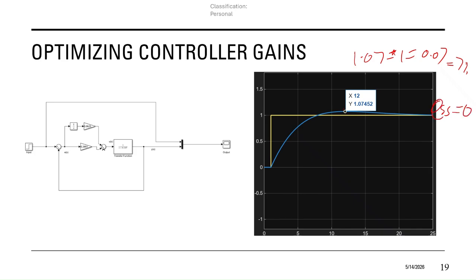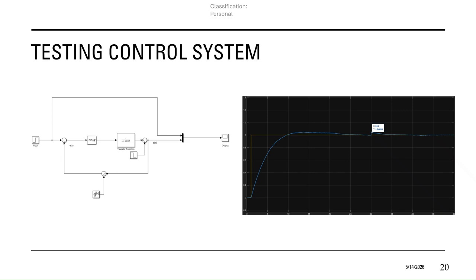And the settling time is less than 20, meaning that this has completed all my conditions. And now that I have designed a control system, I want to see how my control system fares when it's given tests. I'm going to give it 3 tests: a reference change, a disturbance, and an actuator limit.